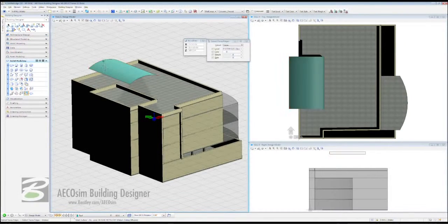And now we need to be able to connect our walls to the underside of what is our curved surface, but it's got to be called a roof first. So we're going to come to our solid modeling taskbar, to the fourth row down, second icon in, modify solid entity. And inside there we're going to choose a second icon interface. Our distance is going to be 1 foot, and we're going to extrude the faces.